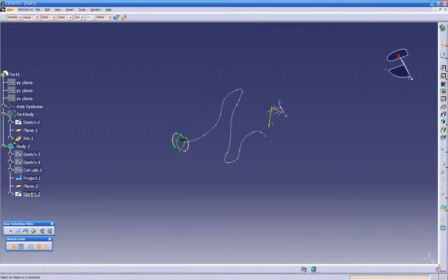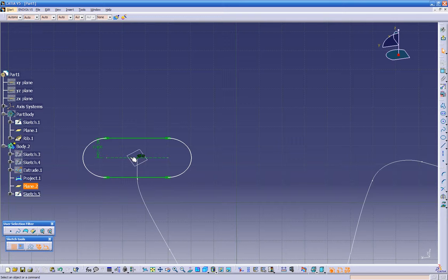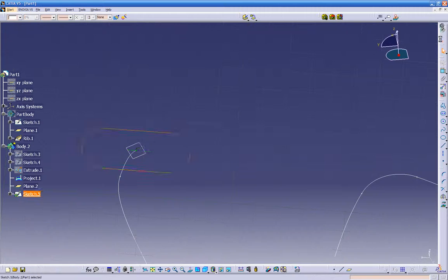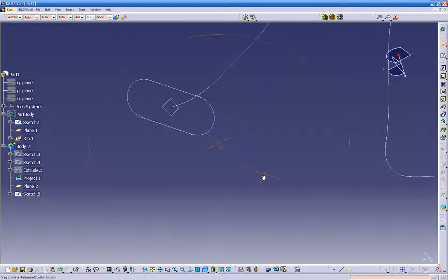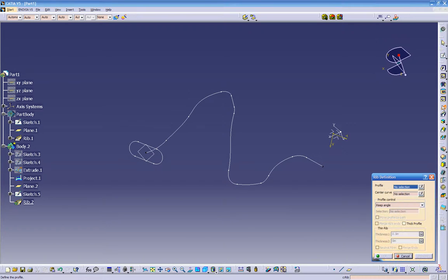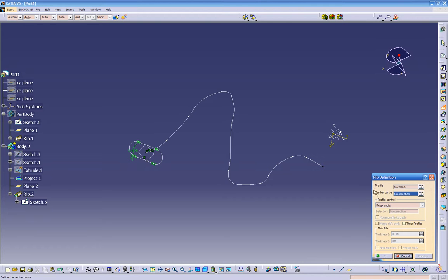Let's go back into our sketch, and I guess our point, see this, I don't know how come I didn't pay attention, but this is not on. So that my point in here is not set for the construction element. So just click on this. Now once I get out of the sketch, we don't see our point anymore. So now we can go back to the rib option, and we shouldn't get the error anymore. Click on the profile. Now click on the center curve.